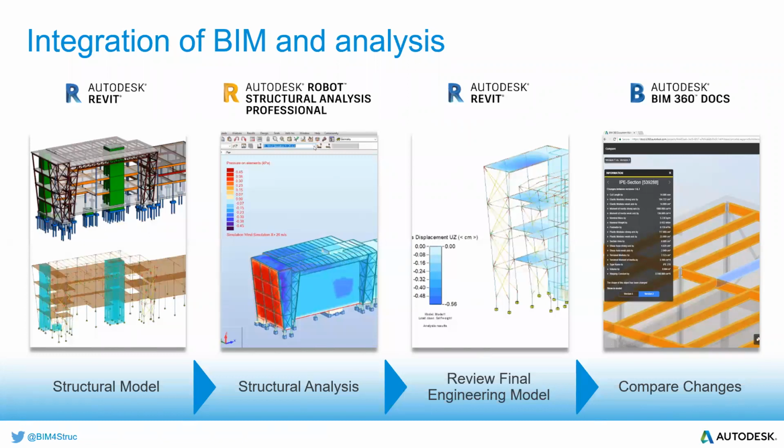And as we remember, an analytical model basically gives us the nodes and the joints, plus the various support conditions and boundary conditions of the model that you are proposing. Then after that, the structural engineer will define his loads, that is the dead loads, the live loads, and also the dynamic loads, that's the seismic plus wind loads. Once all those parameters are identified and agreed between the structural engineer and the structural designer, they can proceed to the next stage, where they perform analysis of the same. And this now happens within Robot Structural Analysis Professional.